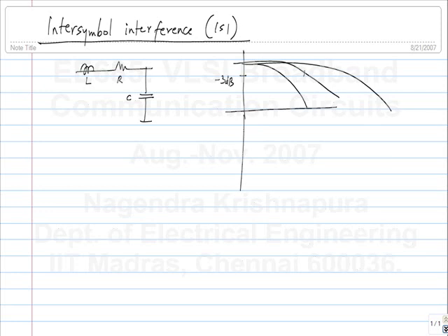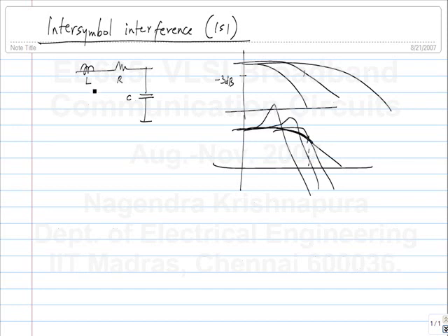So what happens is, let's say this is the response of the RC filter. For very small values of inductance, not much happens. It may have some changes here and so on. And then you can always find a value of inductance where it does this. It becomes a second order Butterworth filter. And if you increase the inductance beyond that, what I believe will happen is it will start peaking as well as the bandwidth will reduce. Because here the variable is L. So as you keep changing L, this is what will happen.